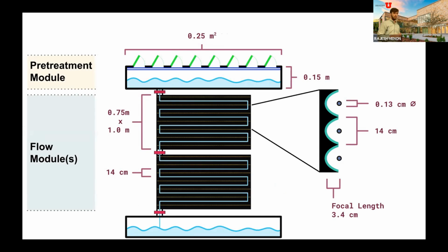But there is no pump, right? There's no pump, it's gravity driven. So you have a specific height for the pre-treatment module, which, plus the diameter, will determine that flow. Yeah. Okay. In addition to various friction coefficients that are calculated for bends. Yeah. I'm assuming those are fixed basically by the materials. And maybe the diameter will affect it a little bit.